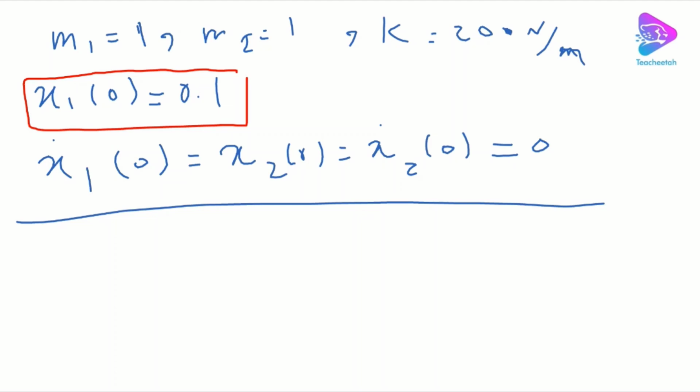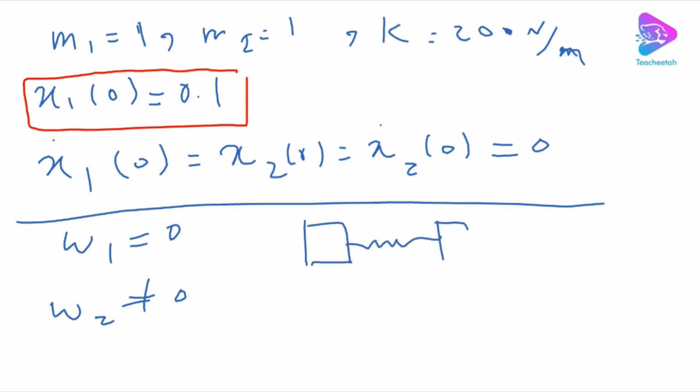Before we end this session, I just want to explain a little bit what it means that we have a frequency of 0 here for this case. So we got omega1 equal to 0, omega2 equal to a non-zero value. If we imagine, just as a hypothesis, that the system only moves, let's say moves, not vibrates, using the first mode, the whole system actually moves together like a rigid mass, everything goes one way together, and there is no relative motion in between.